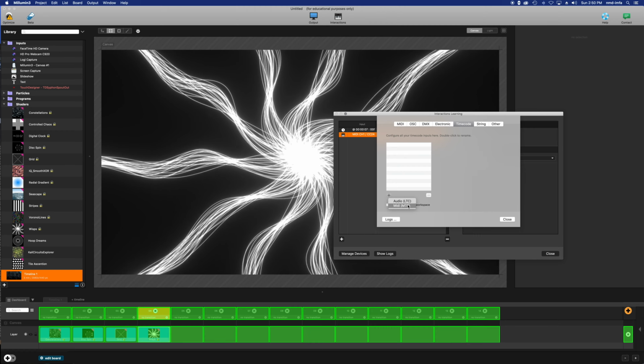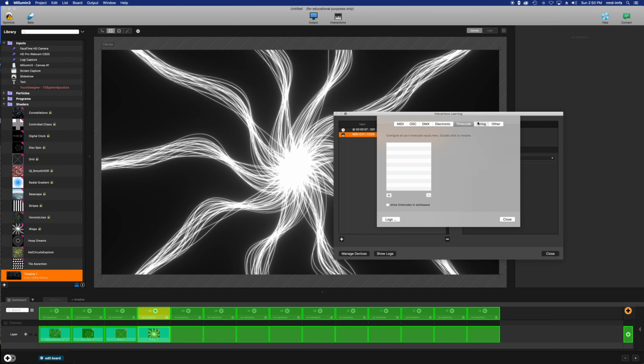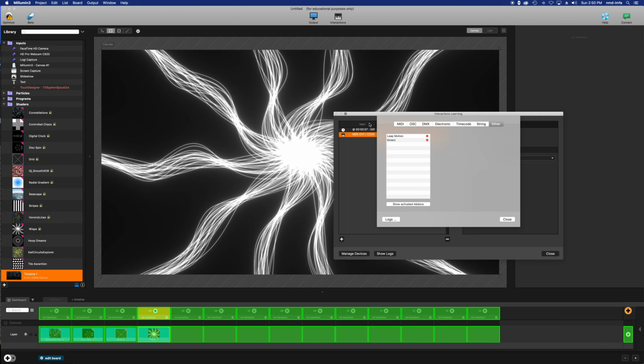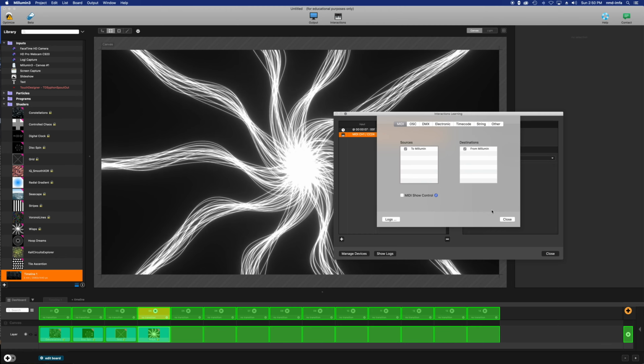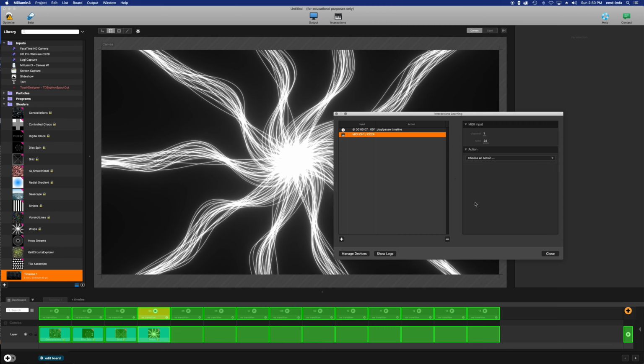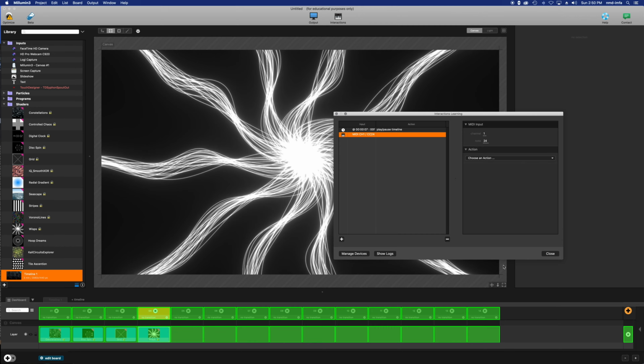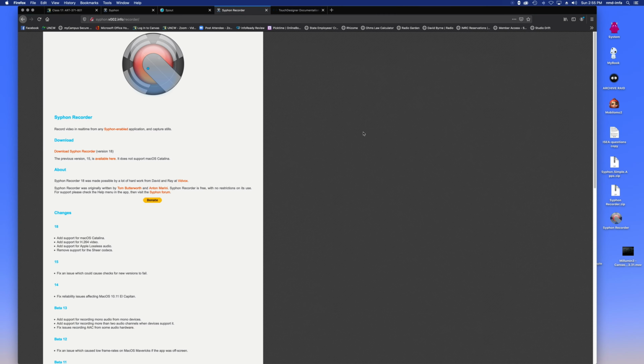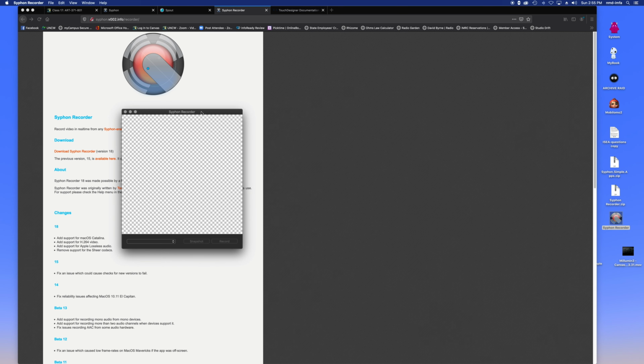Cool. So we'll get back into interactions, but I wanted to just introduce that today along with Syphon, and hopefully it allows you to expand out a little bit and see what all Millumin has to offer. I almost forgot, I wanted to show you that there's a great app on Syphon's website called the Recorder. It's a great little system that allows you to just record your output from your mapping software. So if I open up Syphon Recorder right now, there it is.